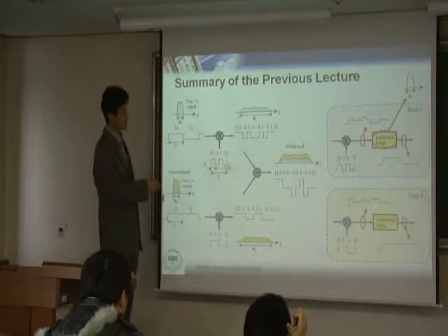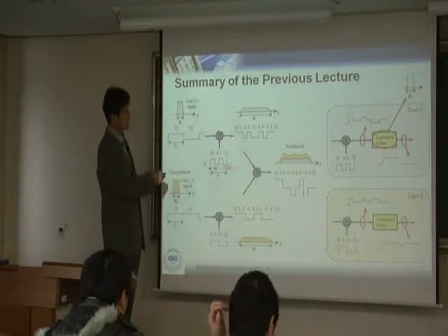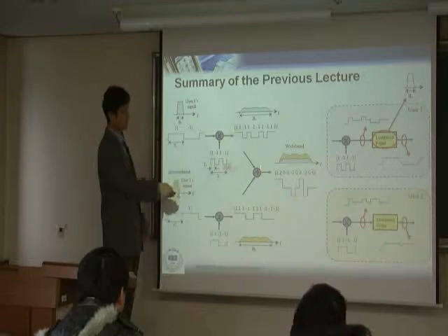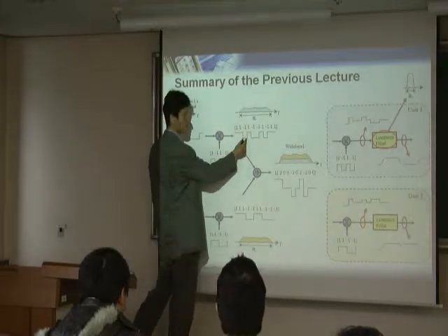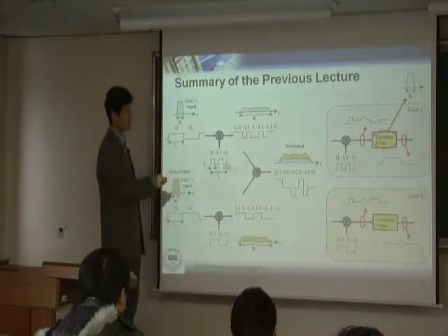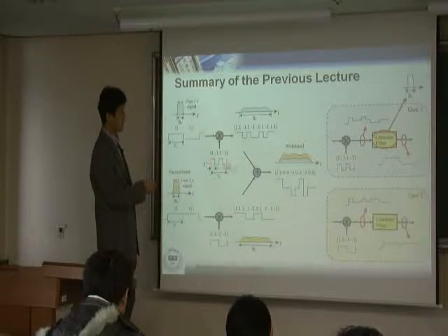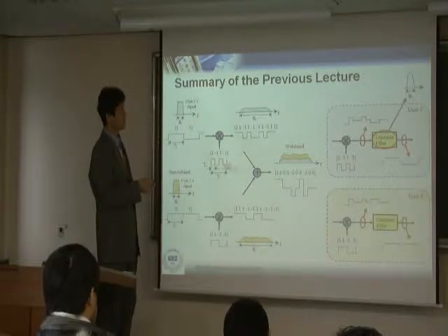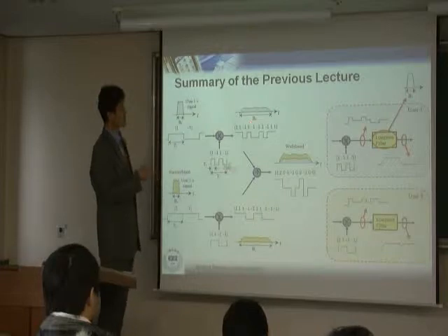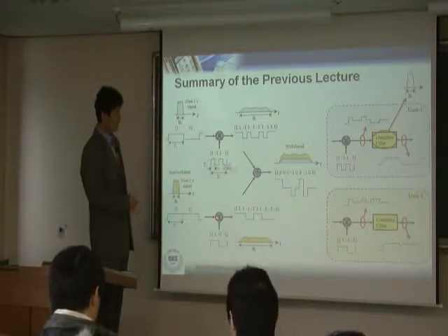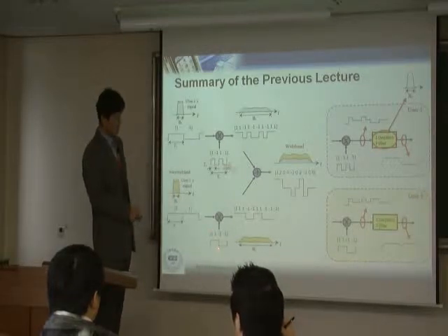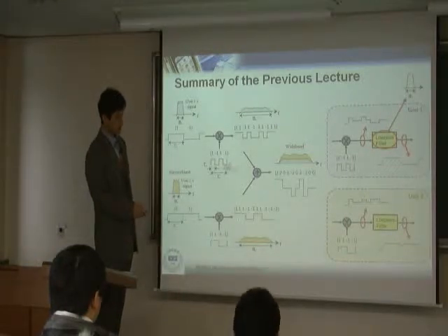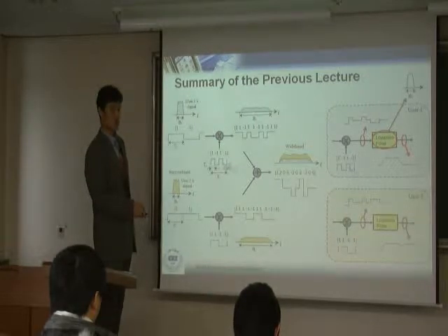So once you multiply your code into each bit, this information is converted into this rate. From the channel's perspective, the duration is now the chip duration. This chip duration decides your bandwidth, and now you multiply this fast chip rate, so your bandwidth is spread. This is why we call it spread spectrum. This is what the spectrum looks like for user 1's signal after you multiply your code. Same way for user 2: this was an original narrowband, but once you multiply your code, since the code is based on the fast chip rate, the signal is spread. So this is the spectrum for user 2's signal.